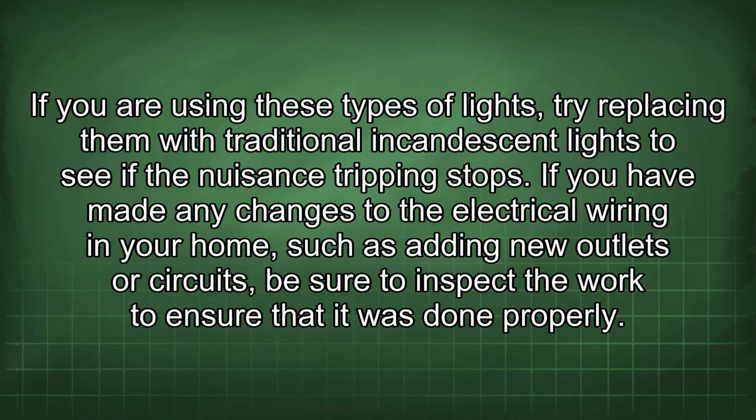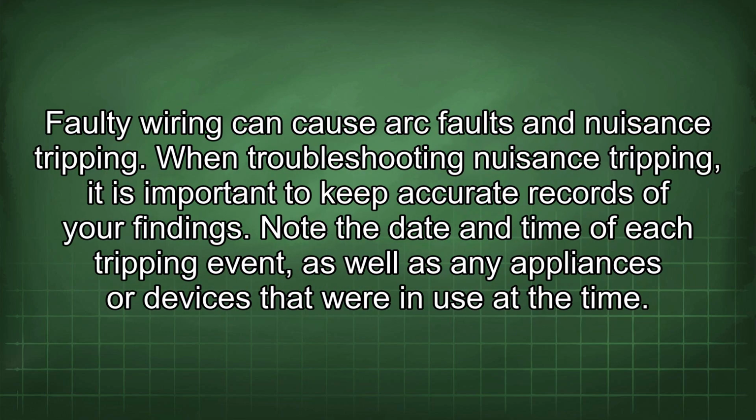tripping stops. If you have made any changes to the electrical wiring in your home, such as adding new outlets or circuits, be sure to inspect the work to ensure that it was done properly. Faulty wiring can cause arc faults and nuisance tripping.